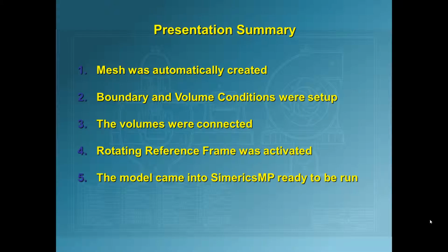So in conclusion, to summarize, we exported a blower created in CFturbo into SimericsMP and saw that the mesh was automatically created, the boundary and volume conditions were set up, the volumes were connected, and the rotating reference frame for the rotating parts was activated.